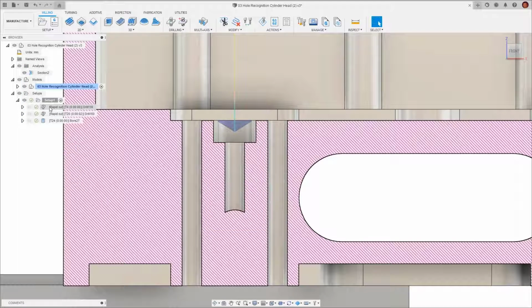Hole templates are the toolpaths needed to create that specific signature. Going back to the counterbore example, we may need a spot drill, a deep drill, and finally a 2D bore operation, all in sequence to create this geometry.